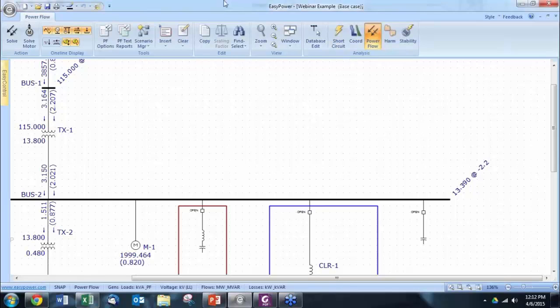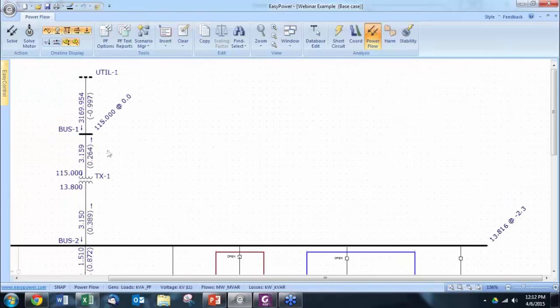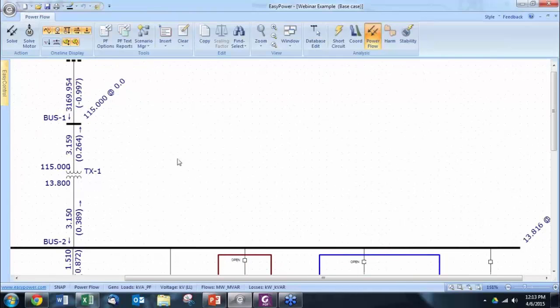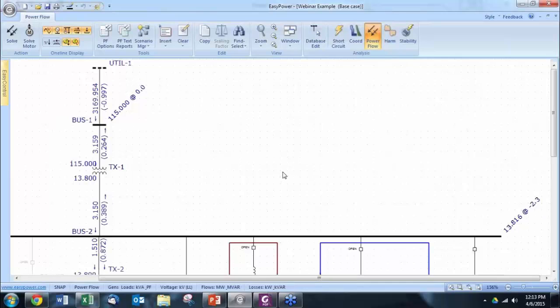The capacitor bank, and then we energize the bank, which is giving 2,400 kVAr. And then, of course, now the plant is not consuming reactive power. It is providing reactive power to the grid. And we have a capacitive power factor beyond 1. So the economic problem is now solved. In your monthly receipt, the utility will even give you, at least in Mexico, a little bonus for having a high power factor. So that may seem to be the end of it.